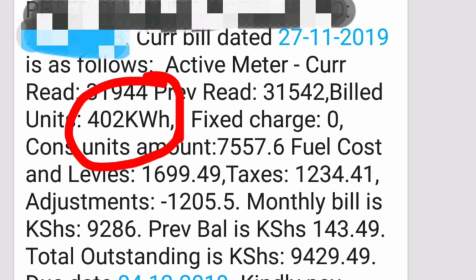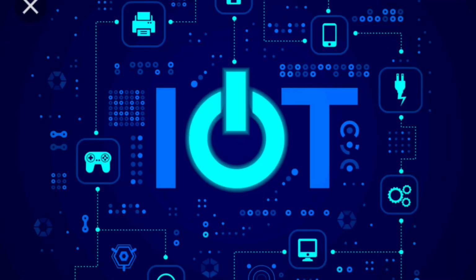So in this scenario, we've been able to demonstrate the power of using connected devices, and our meter was connected to the internet. We were able to log data every 5 seconds, and that data was plotted and analyzed, and we were able to point out exactly where we had a parasitic load, and now it is much easier to manage that load.